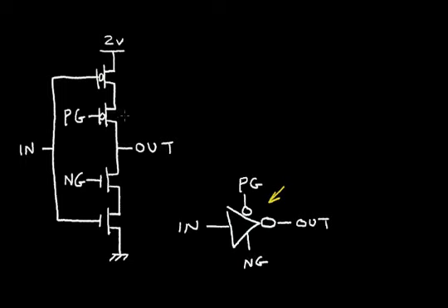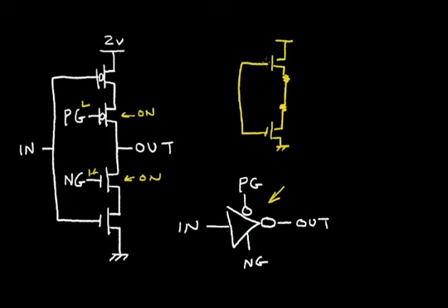Now let's consider again the operation. If our switch circuit is closed, if this transistor is on, which means this corresponding gate is at a low voltage, this N channel, if this gate is at a high voltage, this N FET is in the on condition. And that can be thought of as an inverter circuit with a small resistor in the drain and another small resistor forming the N channel to the N FET to ground, where the gate of this N FET goes to the gate of the P FET. So it forms the inverter function, but this P channel transistor is just a resistive device, and this N channel you can think of as a resistor. So the function is just like an inverter.